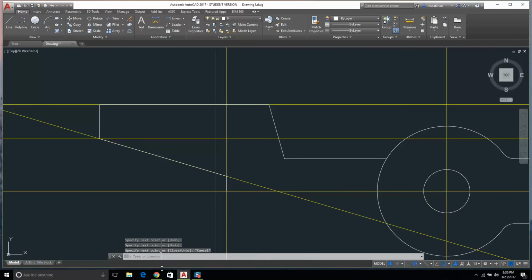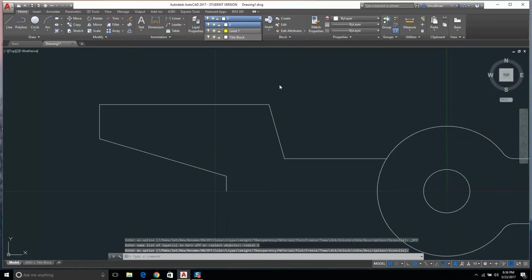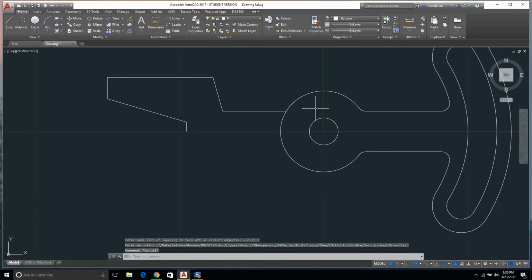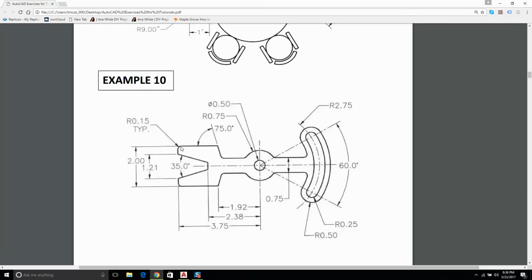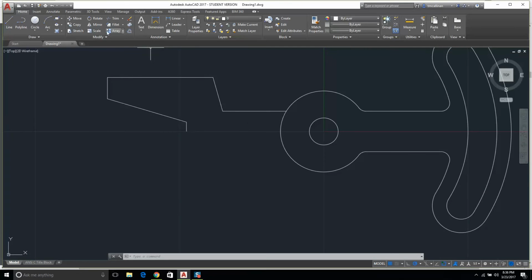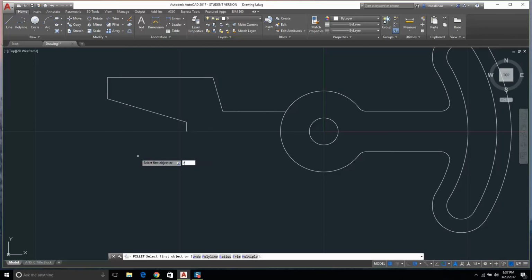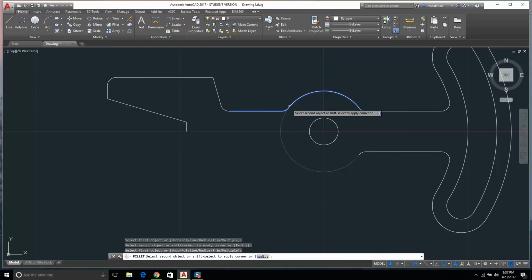Yeah. Now, I'm going to turn off my construction, and I'm just thinking aloud here. Okay. I have fillets there, I have fillets there, and I have 3 fillets. So can I remember where they are? Fillet. I'm already after forgetting. Alright, 3 fillets. For radius, 0.15, I go 1, 2, up again. I should hit M for multiple. M for multiple. I go there to there and there to there.